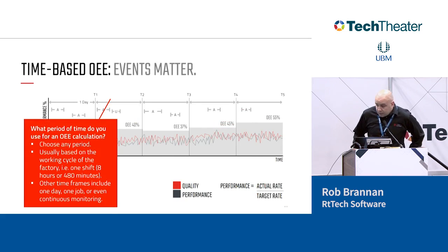So people measure OEE different ways. It really depends on your process and how busy you are. Some operations are 24/7, some aren't. People typically will do it on a shift by shift basis. So like I said before, depending on your shift patterns, it could be an 8-hour shift that you run, or a 10-hour shift or 12-hour. People can as well break it down to individual product runs. It really, again, depends on your process.